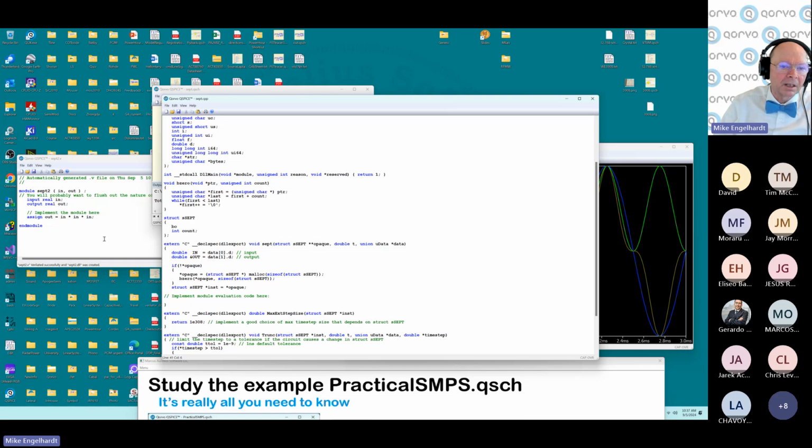But the other thing I need is, a counter has to be edge sensitive. It doesn't make any sense to me to have a counter which counts levels, because if you just hold the level, all it's going to do is just count as fast as it can. So you really have to detect the edge, and every time you get an edge, you will count. So that means that anytime you have an edge-sensitive flip-flop, there's actually two flip-flops in there. One flip-flop stores what the clock used to be, and when the clock is true, when it didn't used to be clock, that's the edge. And then it writes the new level of the clock into the hidden flip-flop. It's just the way it is.